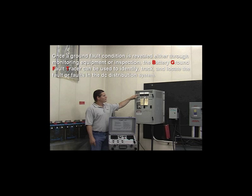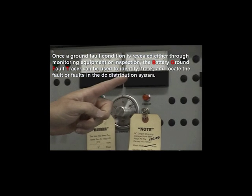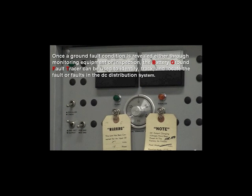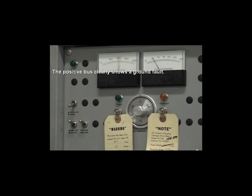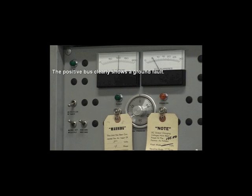Once a ground fault condition is revealed, either through monitoring equipment or inspection, the battery ground fault tracer can be used to identify, track, and locate the fault or faults in the DC distribution system. No ground identified on the negative bus. The positive bus clearly shows a ground fault.